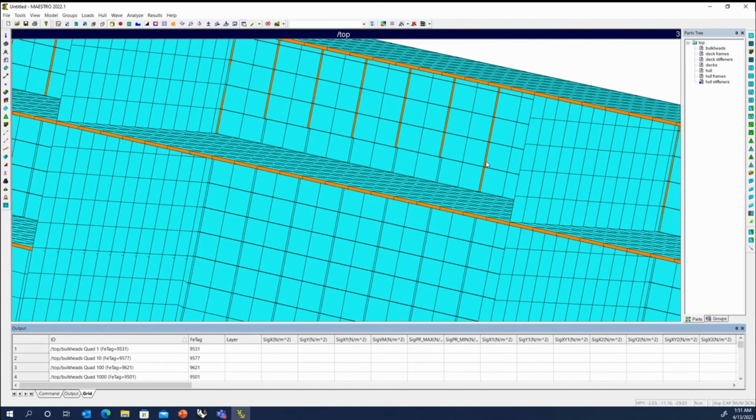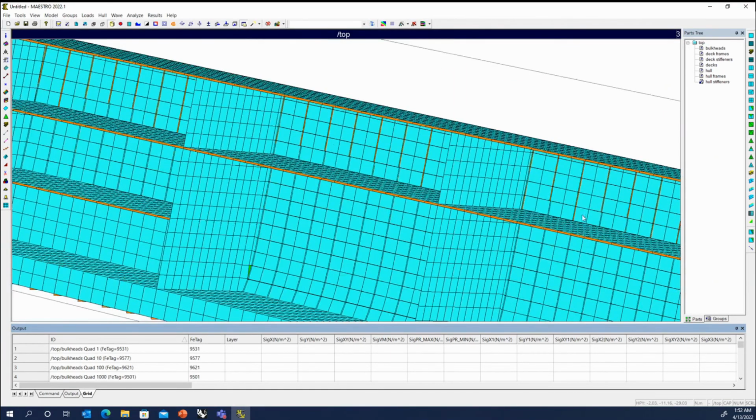And you can see this particular beam segment here must have been ordered from top to bottom, so that the upper node was the first node on this segment. So when it searched for which mesh to use, it found the point on this upper one, and it was pointed inward. So that's why you see that they're not all on that row. They're not all pointed in or out. So that's where you need to be careful of, if you have a beam segment that is on the corner of like a longitudinal and a transverse bulkhead, if you have them both listed as reference sections, you don't know which one it's going to find first.